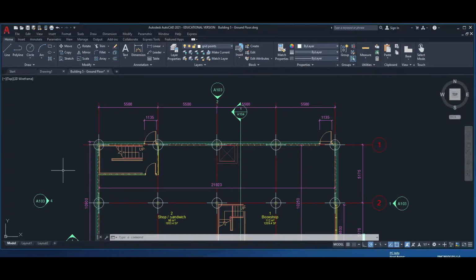So the first stage in working for setting out is we're going to take this drawing and we're going to tidy it up. What I mean by that is we're going to remove all the material that we really don't need. So section lines, text, dimensions. What we want is the basic drawing itself. So we'll go and tidy that up just by erasing